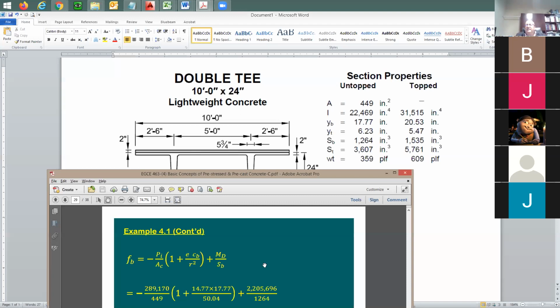Now I'd like to see what's going to happen in this stage. Can I use this equation? You say yes. What P force would I use, PI or PE at this stage? PE. Would I use dead load, or dead load and superimposed dead load and live load? All of them. No, I said I didn't apply anything yet. You remember? Oh, my bad. Yeah. We said that this is going to be right once you move it to the side. I'm going to put this in the building, right? I have a couple of beams. I'm going to just put this in place.